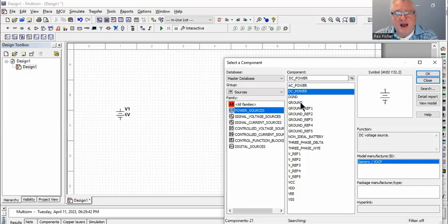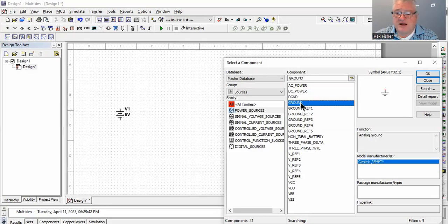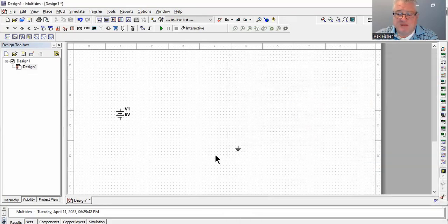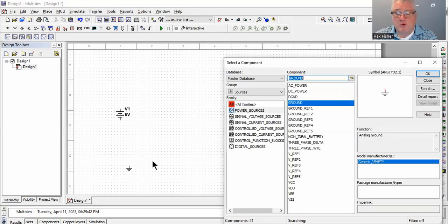You're always subtracting one voltage from another to get the voltage value that your meter shows. So the ground symbol is going to go on the wire to 0 that we're comparing all the other wire voltages to. So there's the ground symbol. I'm just going to put that down here in the corner for now. We'll move it to where it needs to be in a second.